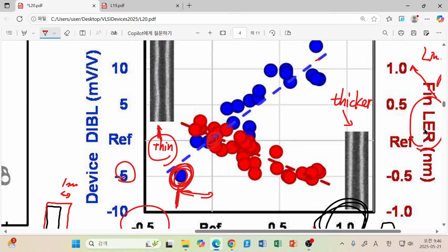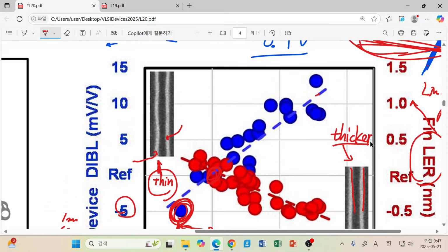So here you can see a little bit of white line, and these two white lines just show the boundary of our FinFET. So when you have a look at this thicker one, you can find that this relatively white region is just straightforward. Here you have the straight line, and when you have a look at this relatively thin case, how does it look? It's just a wavy shape. So you can see that. It is not completely random, but it's some such kind of smooth curve, a long range variation of line width. This is the current limitation of our fabrication technology.